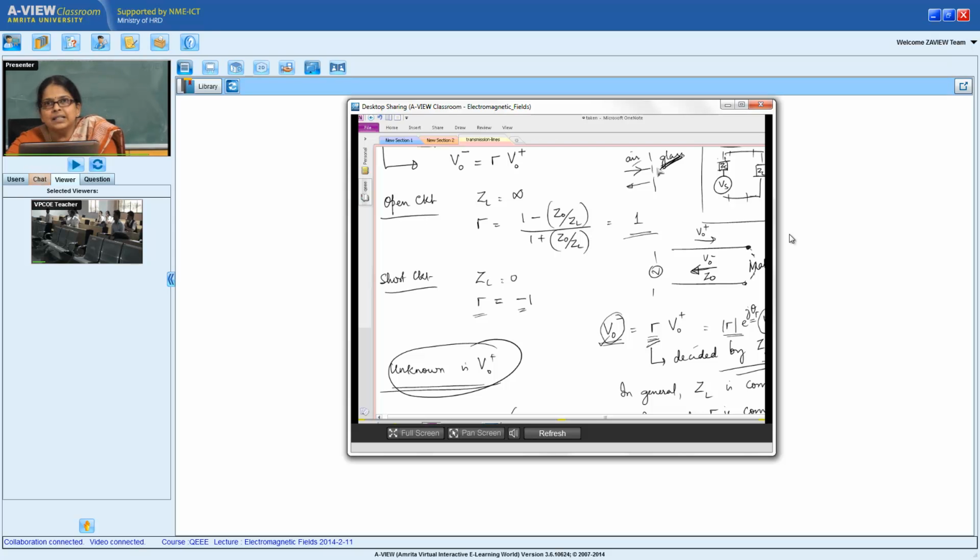Why this is happening in a deeper sense you will understand when we talk about the boundary conditions that the electromagnetic wave has to satisfy. When you are talking about voltage and current waves, what actually is propagating is an electric field and a magnetic field, and Maxwell's equations demand that the electric field and the magnetic field have to be continuous at a boundary everywhere.